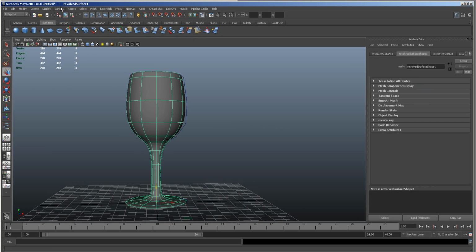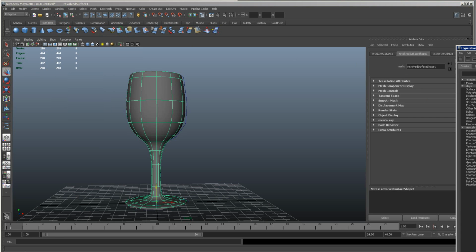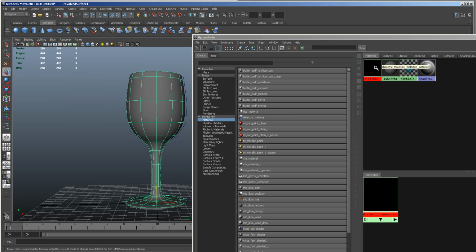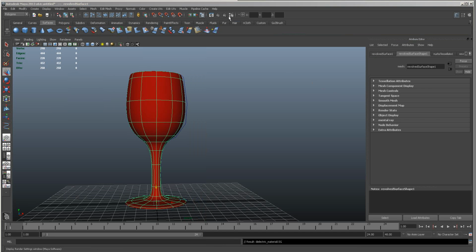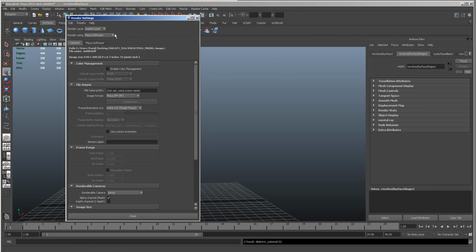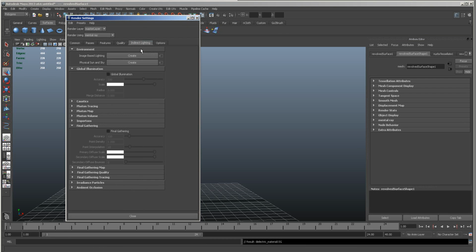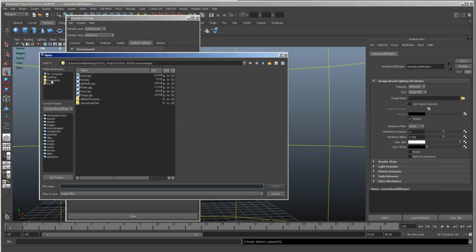So there you go, and then of course I could put that into a material, go render in Hypershade, and I could put it into, say, something like a dielectric material, which will give me a good glass effect like that. And then of course I could come up here. This isn't part of the course, so I'm just shooting through this, turn it into mental ray, because otherwise when I do a render, the smoothing won't work if it's not on mental ray.